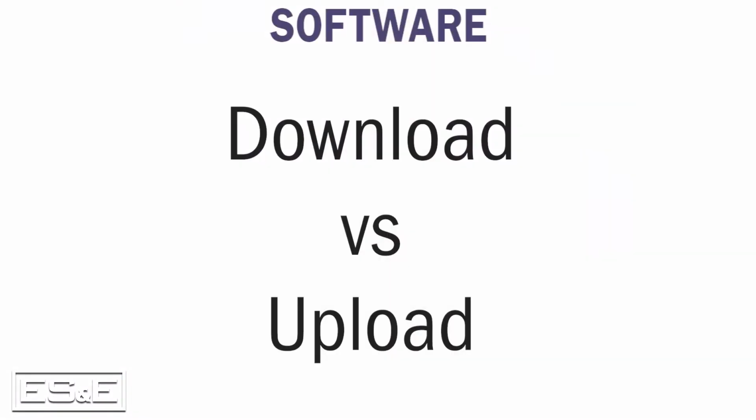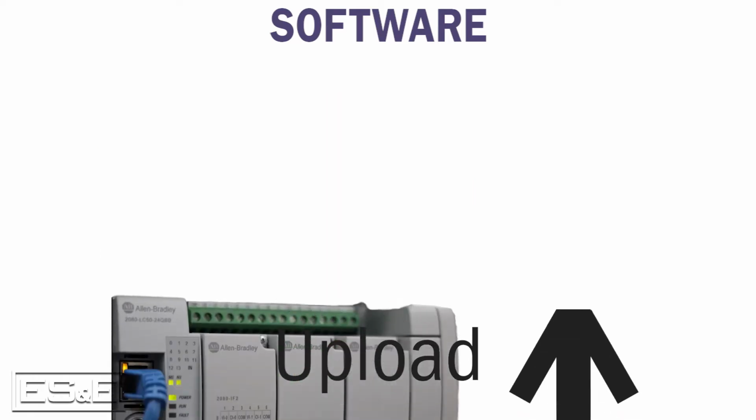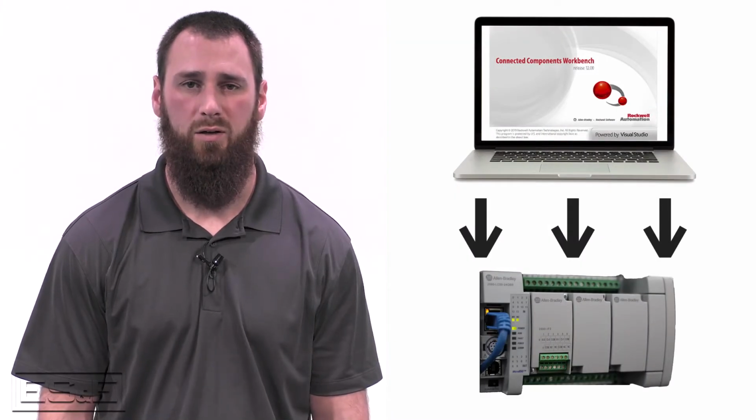Rockwell software always uses the terminology of download versus upload. Downloading is compiling the connected components file and storing that information into the Micro 800 PLC. Uploading is taking that information that has already been stored in the controller and reconstructing the project in your laptop. Doing a download will break the communications and override the instructions that are inside the controller.